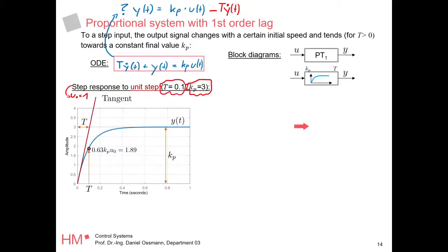So why is this called the time constant? Well, it tells you how fast the system reacts. It tells you about the time it needs to change to the value you want. You can really think of this parameter in seconds. If t is 1, but we make it 10, then we subtract even more, right? So the bigger t is, the bigger the time delay is, because we're subtracting more from our output. So we need more time to get there.